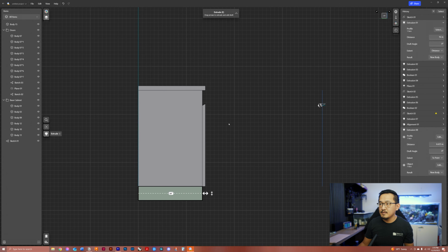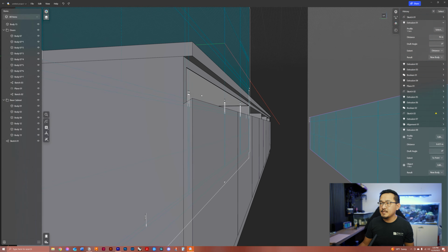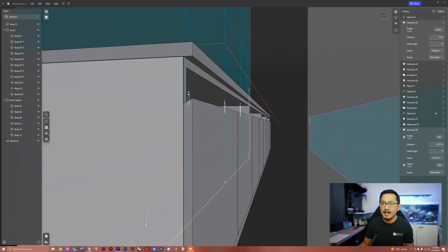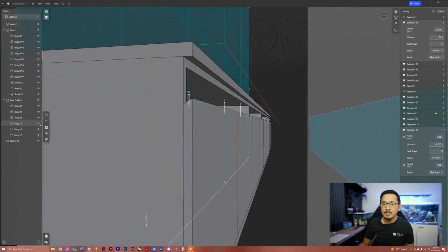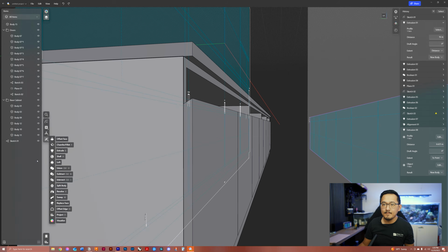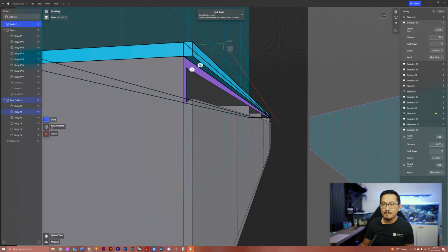16. There we go. And then, as you can see, there is this gap in between our door and the countertops. That's because we need our profile to be actually 3.5 inches. So I need to extrude just this edge here down 3.5 inches. But if I were to just pull this thing down, you can see the entire face comes down with it. So what I need to do is split this face here from the rest of the body. So we're going to hit the split face tool, or split tool, split body actually. Split this using that, and done.